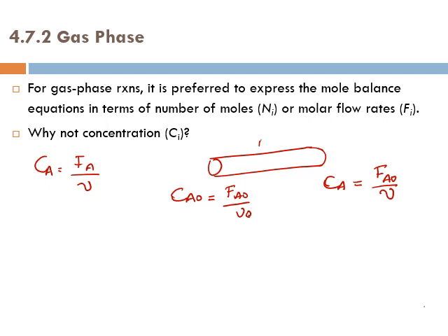When the flow goes through the bed, what do you think will happen to the volumetric flow rate? Since it's a packed bed, the flow will experience pressure drop. So the pressure will reduce, the volumetric flow rate will increase, and epsilon will be greater than epsilon naught.